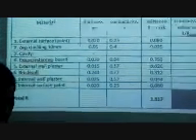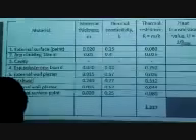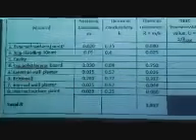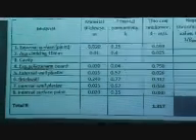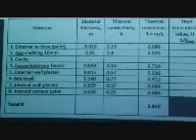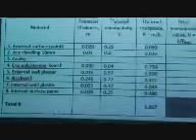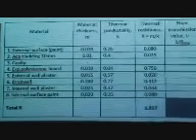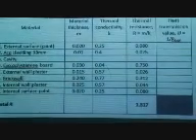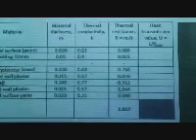And in the table below, you can see the materials that we use to build our wall. The first one is external surface paint with a thickness of 0.020. The second material is ACP cladding, 10 mm. The third one is cavity. The fourth one is polystyrene board. The fifth, external wall plaster. Sixth is brick wall. Seventh, internal wall plaster. And the last one is internal surface paint. And you can see the thermal conductivity of the materials.